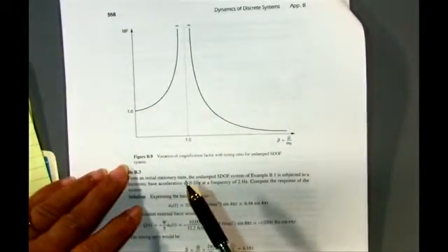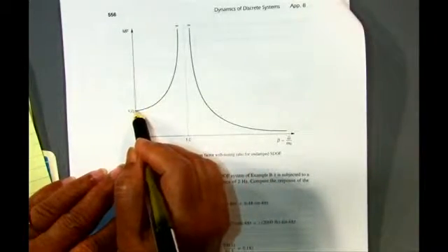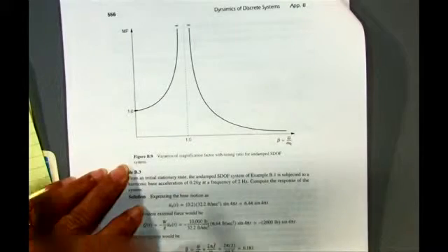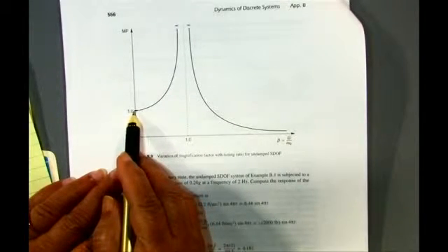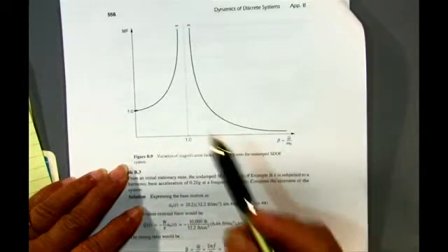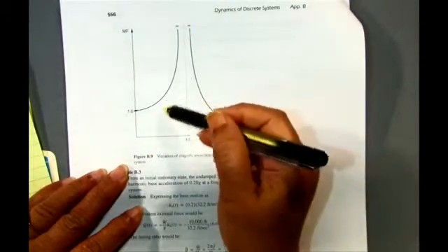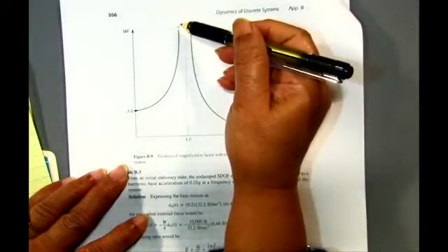So here is the result when we plot beta on the horizontal axis and magnification factor on the vertical axis. What is interesting, you start when magnification factor is 1, which means that dynamic deflections are the same as static deflection, and as beta increases, there are some ranges of beta where very large magnification takes place.